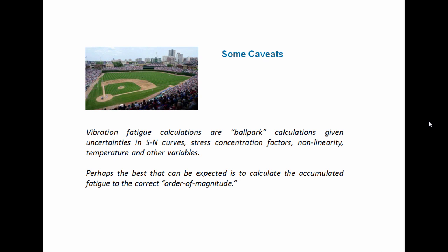There's concerns about whether the stress is one-sided, either in the compression or tensile polarities, or whether the stress field is oscillating about a zero baseline. All these things enter into our fatigue calculations, or at least they should, but it becomes really difficult to get good SN curves that can cover these types of variables.